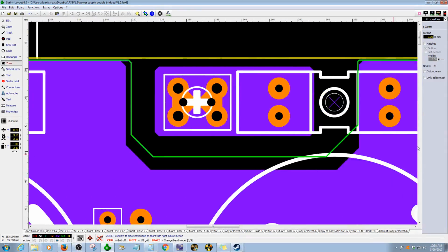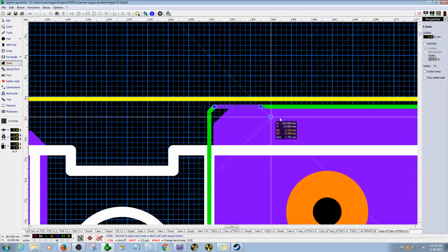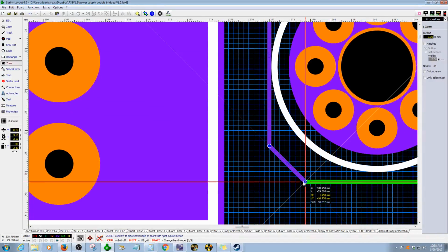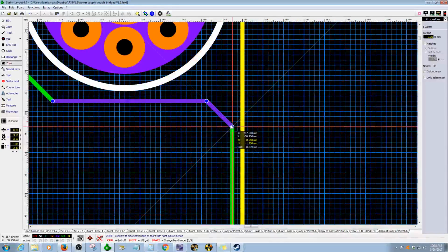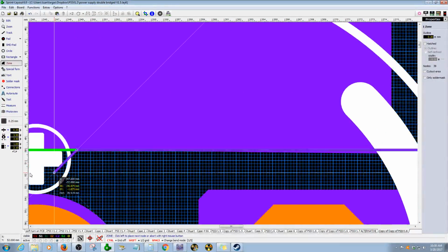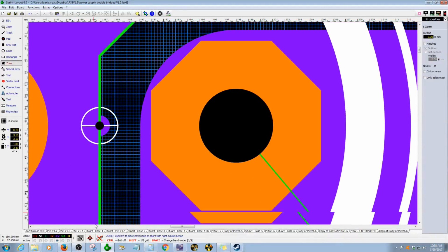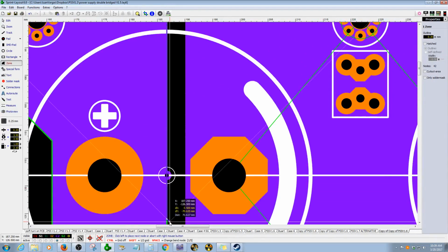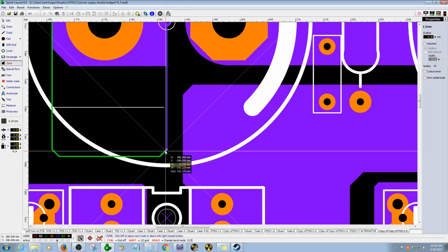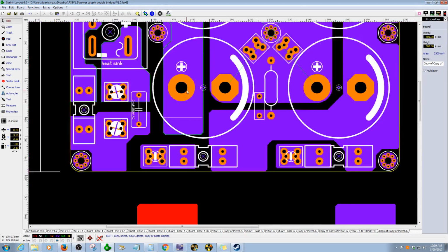So that's why I'm making the video as documentation of how to place or create a copper area using Sprint Layout 6. This is pretty simple. The only thing you gotta do is just trace the line, just follow the green line, the one that I already traced or placed on the design, and continue until it's complete. Do not let go of the mouse until it's complete. So there you go, it's ready to go.